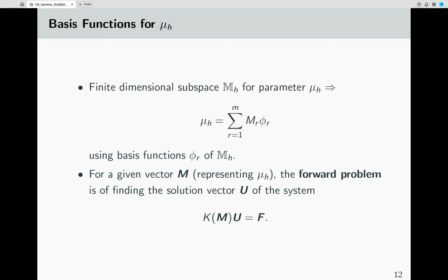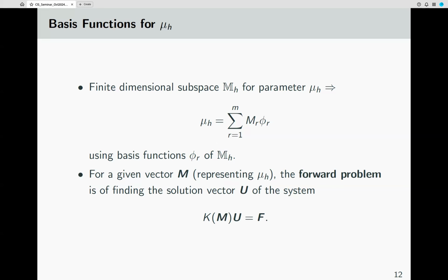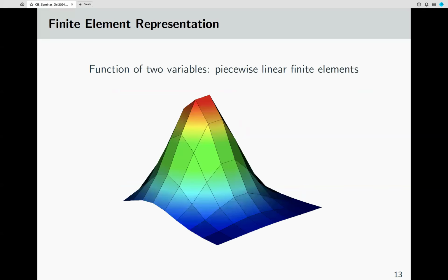And then, essentially it's just a linear algebra problem, right? So in this particular case, because we have a vector problem, that's in the next slide, I guess. So this is basically how it's going to look in the two-dimensional case. Now, I just drew a really coarse mesh, with how many? 1, 2, 3, 4. So 8 by 8. So only 64 little squares.